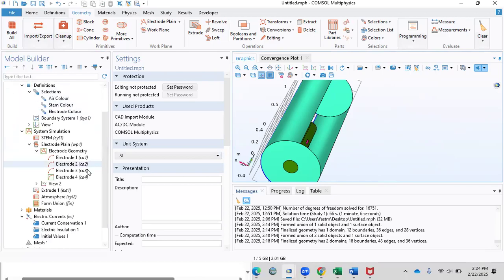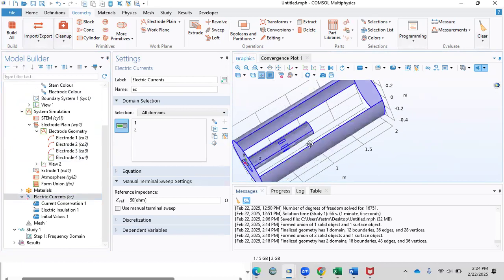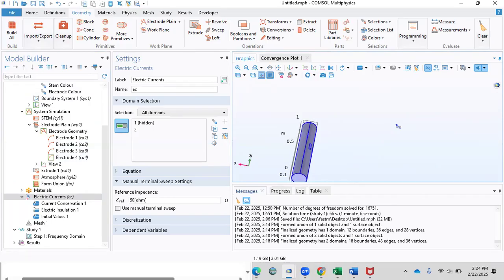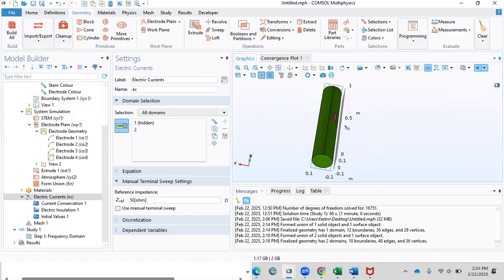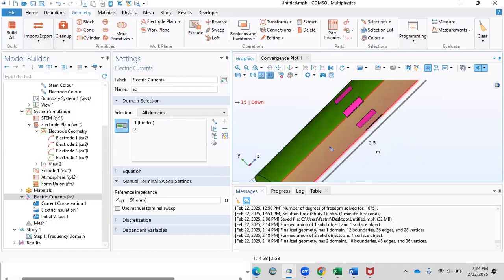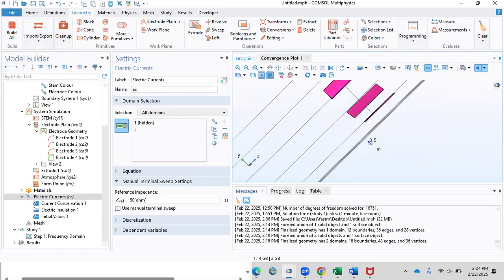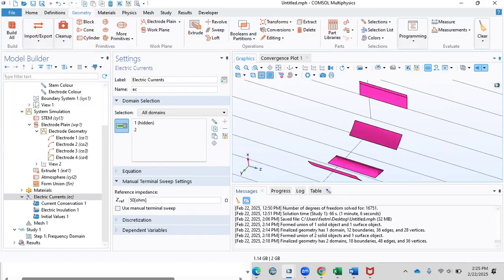Where are we in the stuff? We just created the electrode. So now we gotta put some power to it. So I want to just see the electrode. So what I'm gonna do is remove that, go into boundaries, zoom in on here, and I'll just remove the outer pieces, so I could just have the electrodes now. Deselect it, zoom in, so I could see the 4 electrodes fairly well.